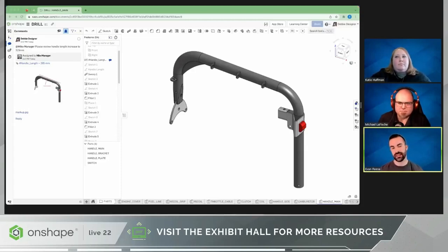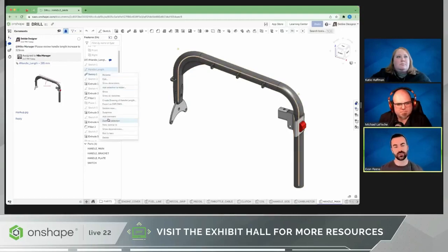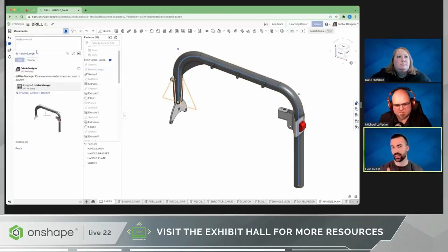So we actually use commenting in Onshape a little bit differently than is being shown in the demo. The demo talks about the design itself, and we use comments to actually talk about the model structure. If you have written software, it's like commenting your code. So we can use comments to explain if we have a master sketch that has a lot going on but controls the whole model. We might use an annotated comment with markup to point at different elements and say what they control downstream. Or sometimes I'll even record an entire video tour of the model structure for the entire document,